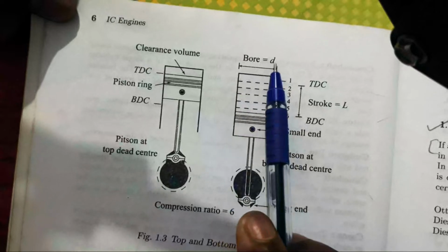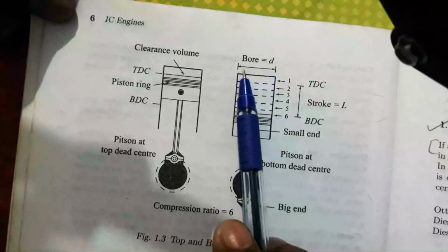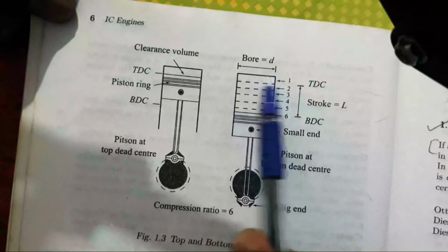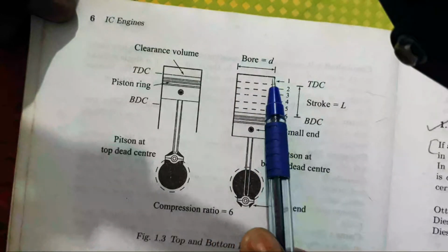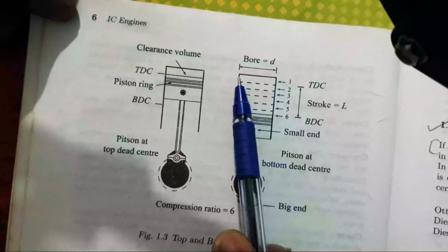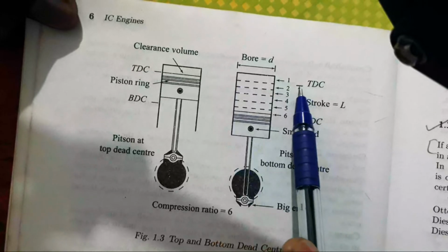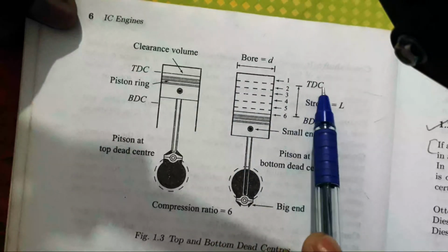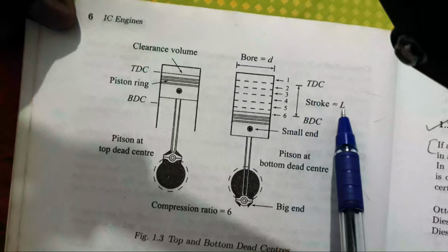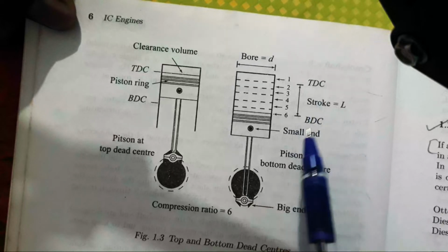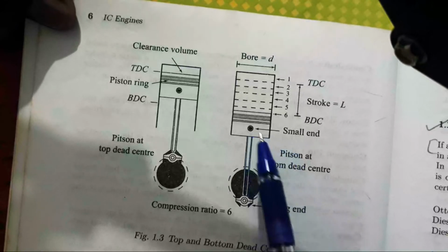Bore means the diameter D. From here to here, this expresses the diameter of the cylinder. The distance from TDC to BDC is called the stroke length. It is represented by capital L. This small pin is called